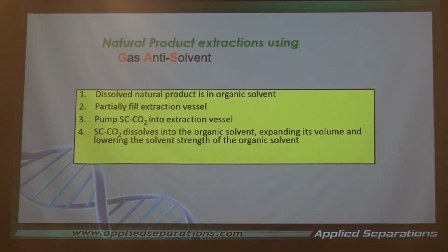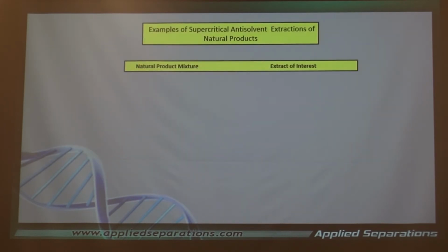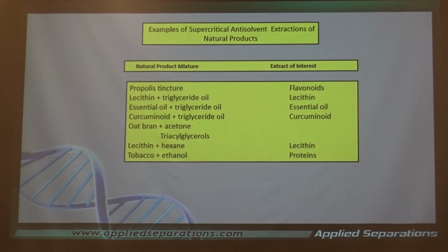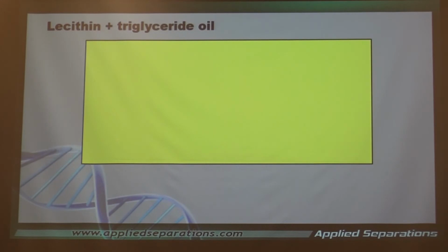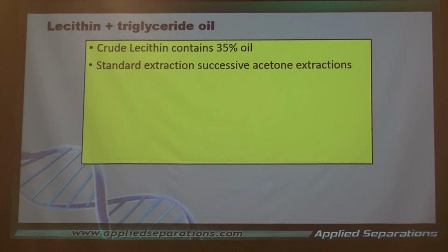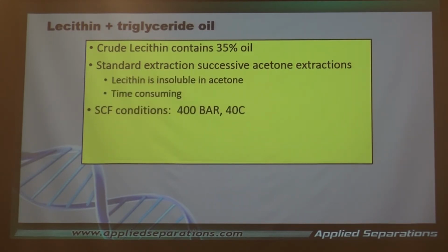And we're going to do exactly the same thing. We're going to go ahead and extract lecithin from the triglyceride oil. The triglyceride oils we saw are very soluble in CO2. So what we're going to wind up doing is, normally this is extracted with acetone. Not a very good candidate, not from an environmental point of view. Lecithin is insoluble in the acetone and it's time consuming.